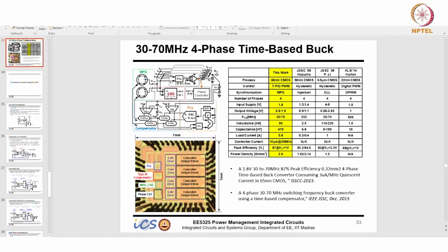And then you can think of the multi-phase generator as nothing but dividing this clock by 4 and separating out all the 4 phases. So a single phase goes here at 4x and is then separated out into 4 phases, rather than tapping the 4 phases directly from the VCO, because that may have mismatch. So here you get a very good phase match.